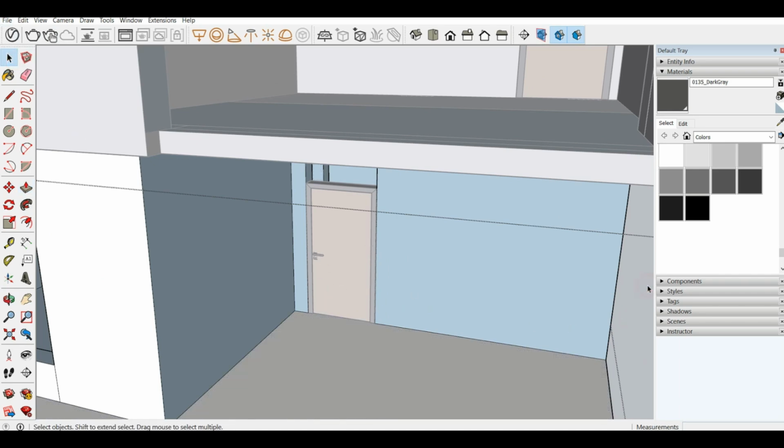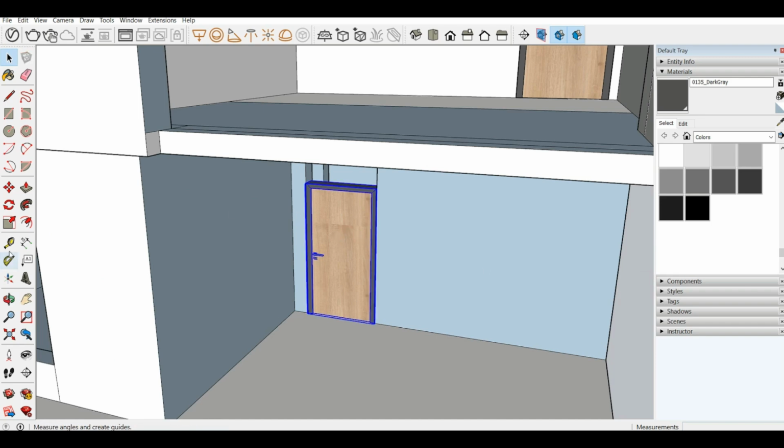So now I'm just gonna select the rotate tool and rotate the door. Now I will demonstrate first. If you wanna rotate any object 180 degrees, all you need to do is click once here. Wait a second. Click once here and drag it along the red axis, and then simply drag the mouse around until we meet the red axis on the other side.